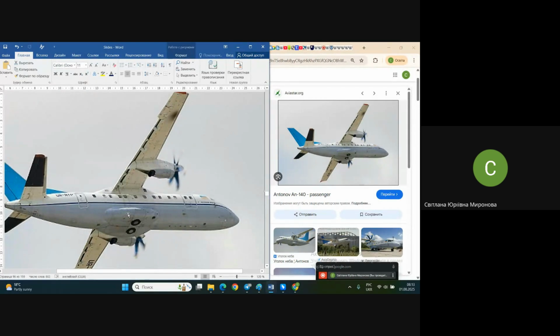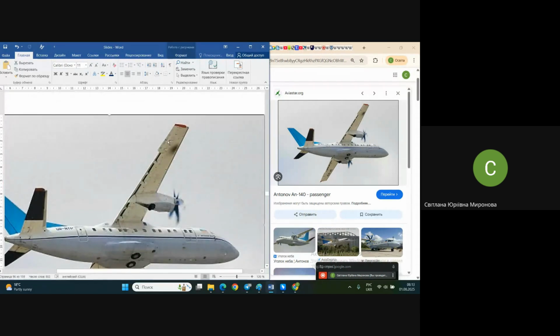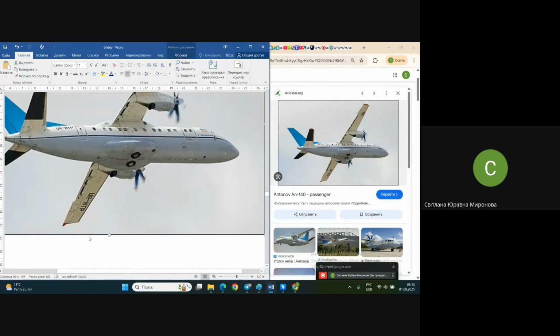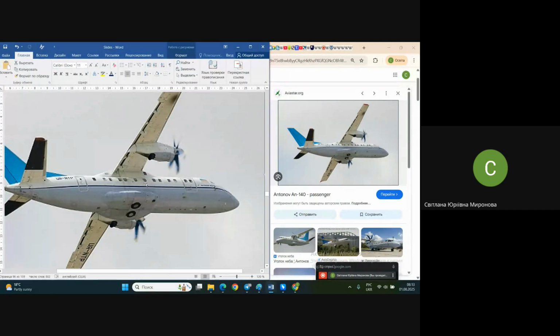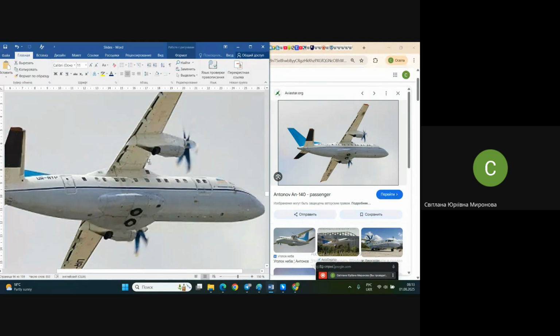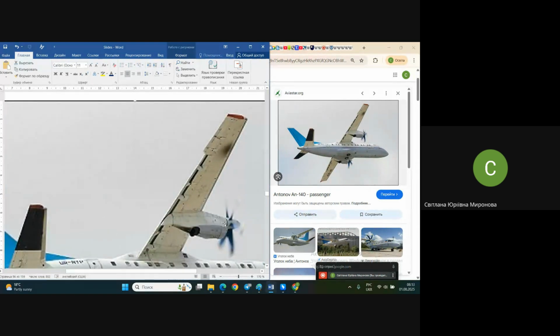It's with retracted, with deviated flaps here. What is visible: the flap deviated, and the aileron in normal position. Seems like at least they are in normal positions, they are not deviated. And pay attention to the engine. It's visible that it's a turboprop engine, and those holes under the wings are for cooling. The engine is somewhere here, lower than the prop.